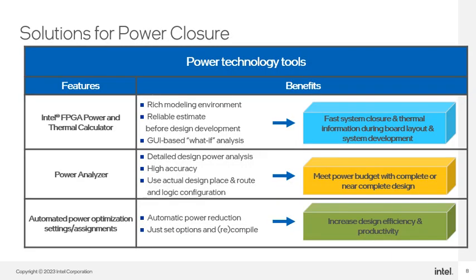Intel FPGA provides the tools you need to close power in your system. At any point in the design cycle, use the Power and Thermal Calculator, or PTC, to model your power requirements and calculate what kind of cooling solution is required for your design.